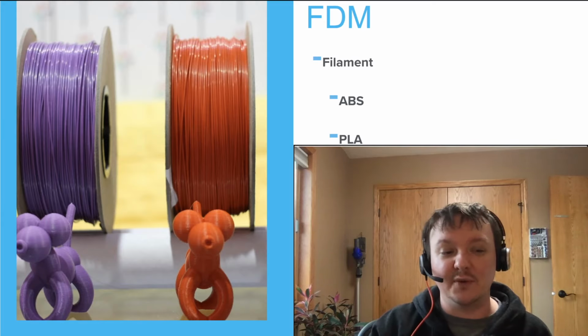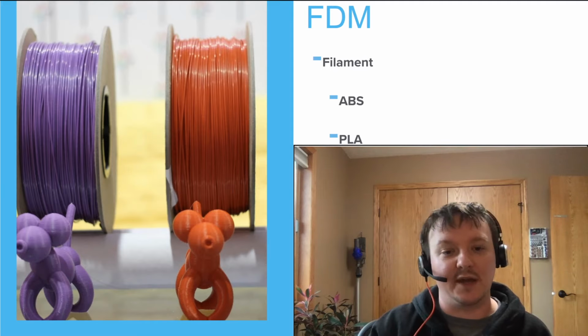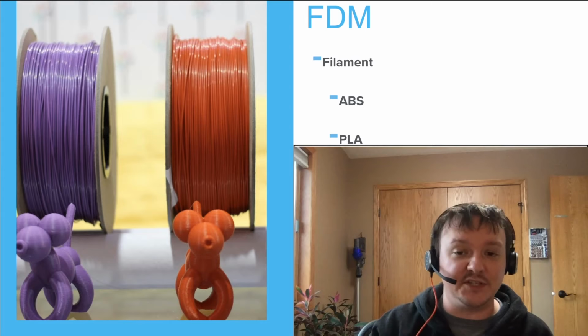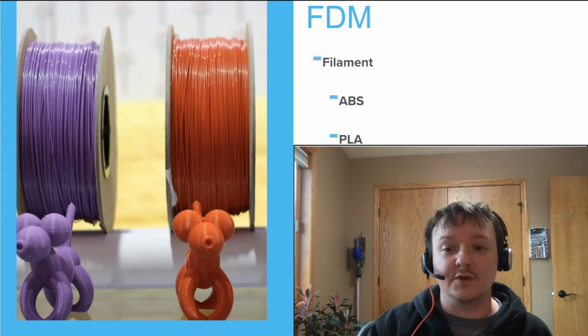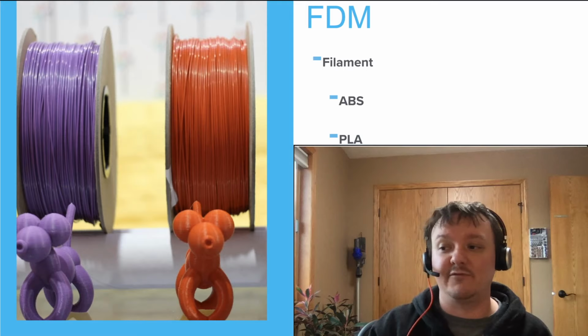So if I'm building anything structural, anything that will hold things together, I'll do that with PETG. There are, of course, other filaments. There's TPU and TPE. Those are usually flexible, which are usually much harder to print. But sometimes if you wanted to print a phone case or a cover for something, the TPU, TPE is used for that.